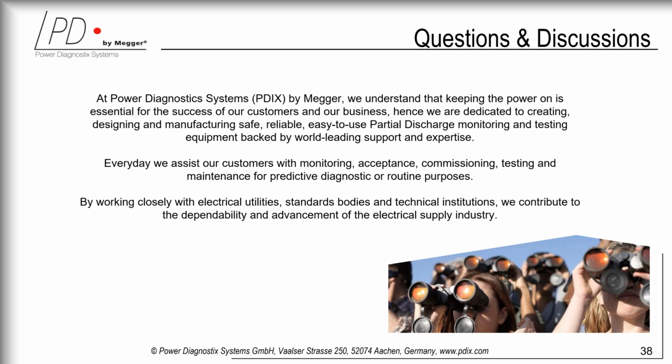So again, we are testing very carefully these bushing adapters. They are made out of aluminum, in the sense that they have a gold-plated contact, and then they have basically a seal, and they are properly screwed into the system. Now, I have to tell you that the voltage that generally is found at this bushing adapter is somewhere around 10, 15 volts, depends on the bushing.